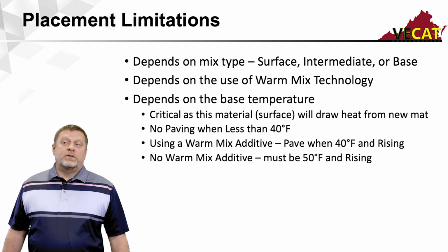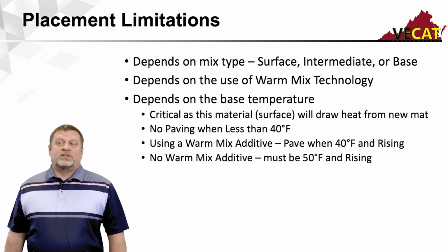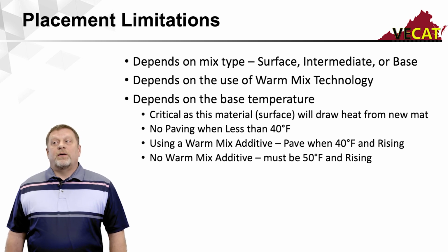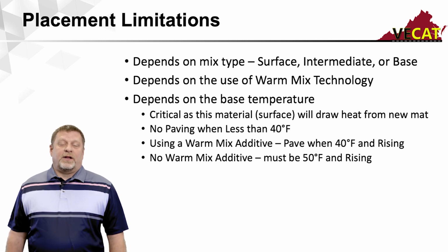One thing to know is that anytime this base temperature is below 40 degrees Fahrenheit, there is no paving. The specification does not allow you to place any asphalt mix when the surface you're applying it to is below 40 degrees. If I'm using a warm mix additive, as we mentioned above, the limit for the surface I'm getting ready to apply the mix to has to be 40 and rising.